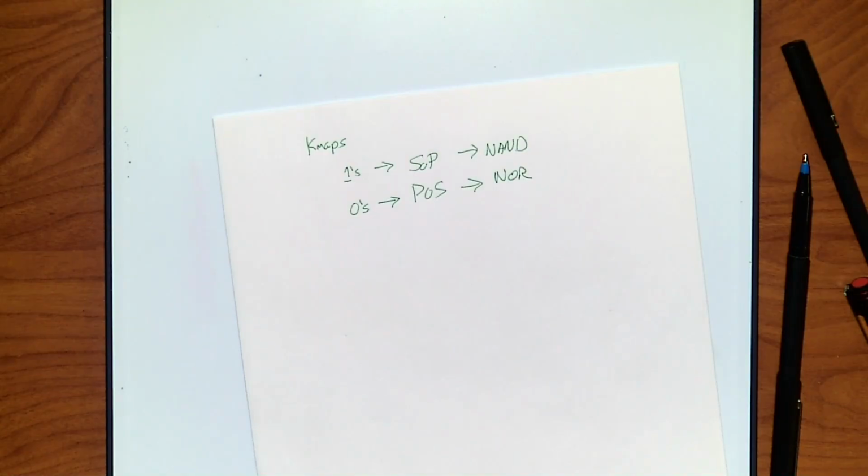I could use these to actually even design my pull-up, pull-down network or my Domino logic setup or whatever I feel like. And then I would probably start with static and then I could easily morph it into dynamic or domino. Okay, these work nicely. Anything else I could do with these?